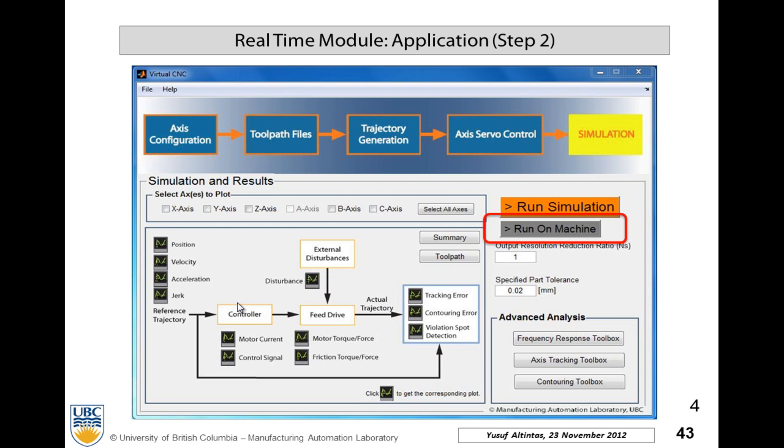And in fact, trajectory generator usually works a few hundred blocks ahead, like a look ahead. That we will also implement here, because we need to look ahead to see the error, incoming error along the path, and compensate the error early on. You can't compensate once it happens, once you cut the path. What we need is enough computer time to calculate and correct the path.